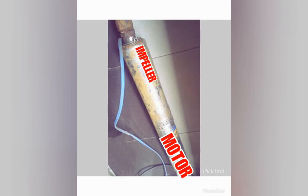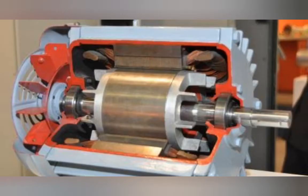AC electric motors, as their name implies, are electric motors that make use of AC sources for their operation. Here we have some subdivisions: the induction motors, the synchronous motors, repulsion motors, etc. Induction motors are electric motors with slip. Slip is the difference between the rotor speed and the synchronous speed. This is explained by the relationship: slip percent equals (ns minus n) divided by ns, times 100.